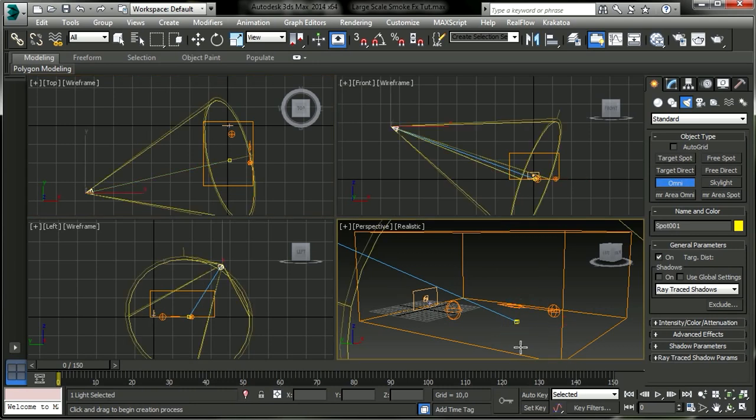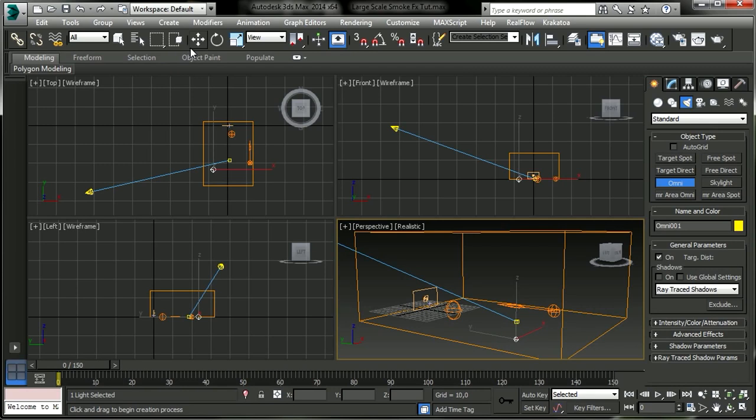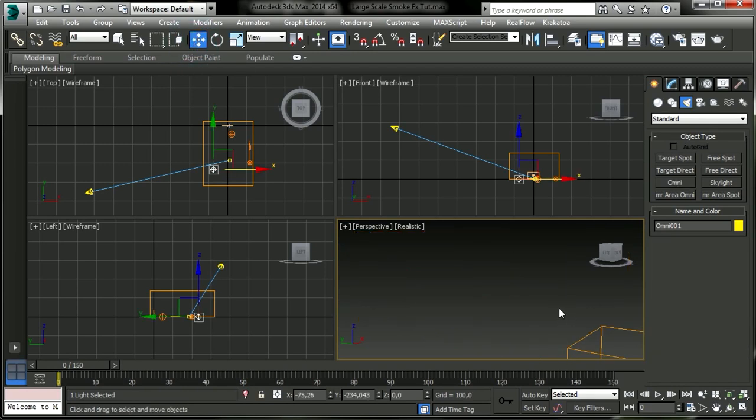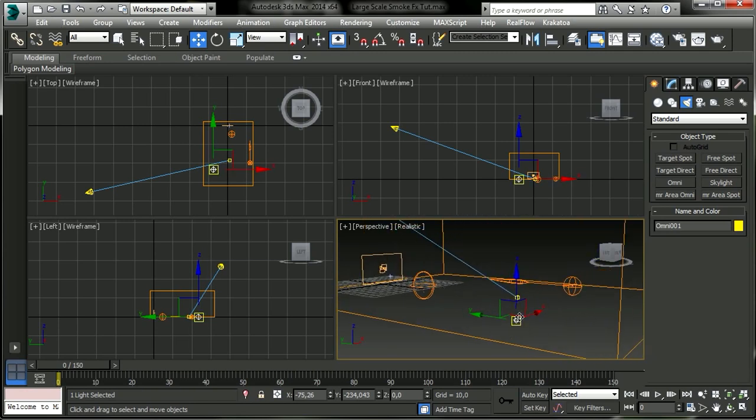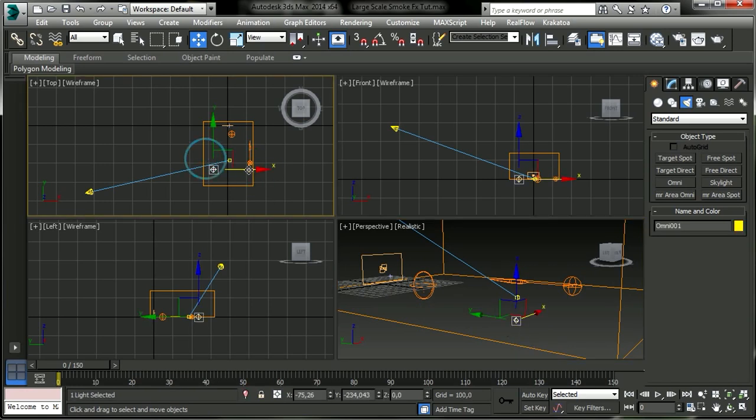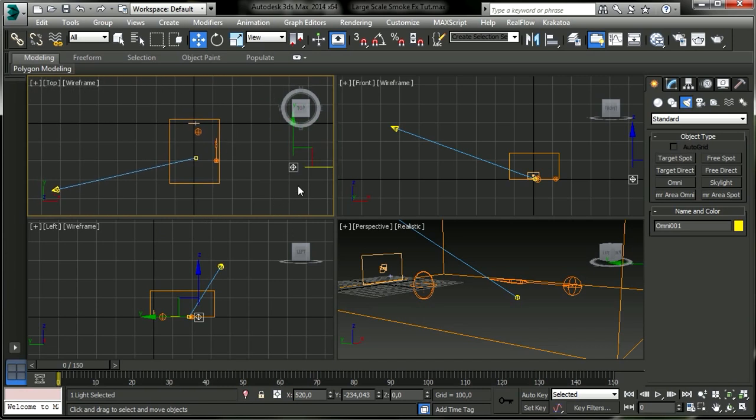Now let's create an omni light, and let's select the position tool because we want to move this. Let's center this view. Perfect. Alright, we want to position this, let's see, on the right for the top view, and down, because considering that my final view will be a kind of lateral, a side view, I want some shadow on the other side, so this will make some nice contrasts.